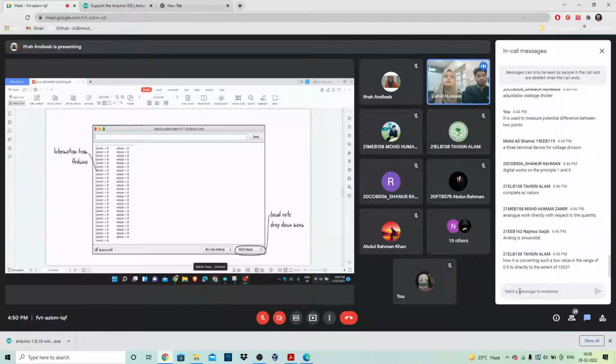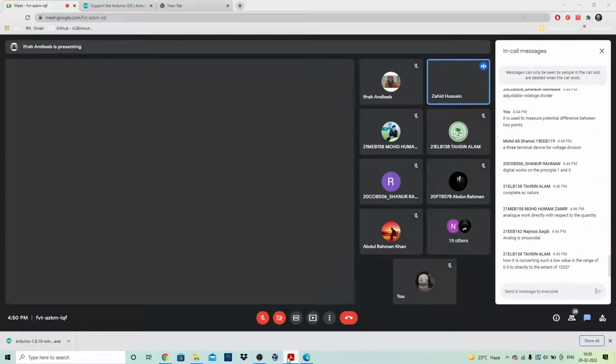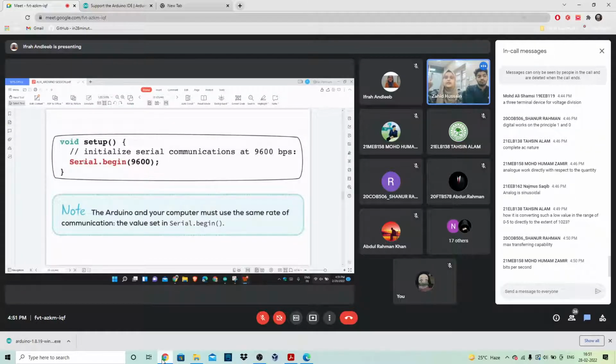Okay. So what happens is, to create a successful communication between us, we have to set the rate at which I am throwing the balls at you, or at which you will catch the balls, right? So we use this part to have a successful communication between the Arduino board and the laptop or the PC that you're using. We set this baud rate equal to, like, 9600 here, and there are more options. You can just drop down and see in the view menu. And then in the code part, in the setup, we write Serial.begin. It's where the communication is starting, 9600.